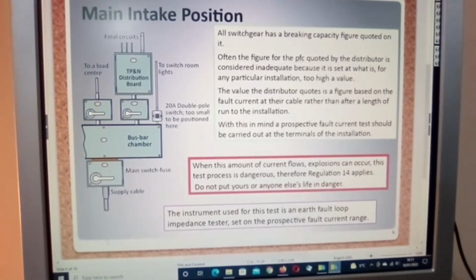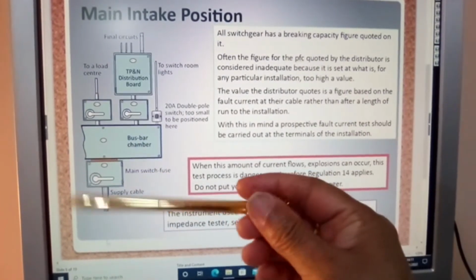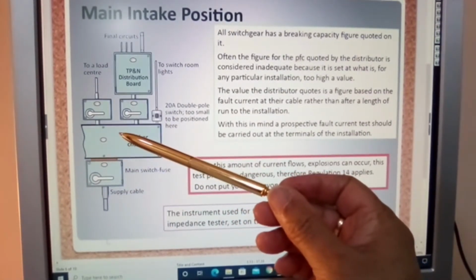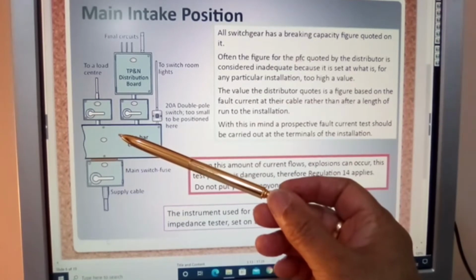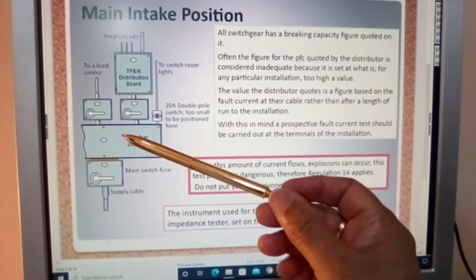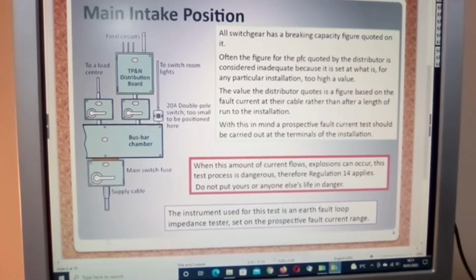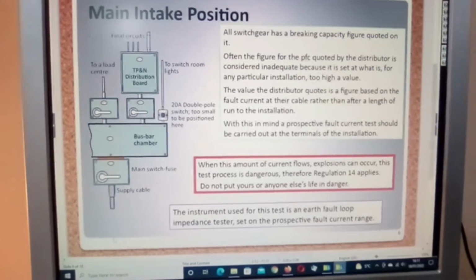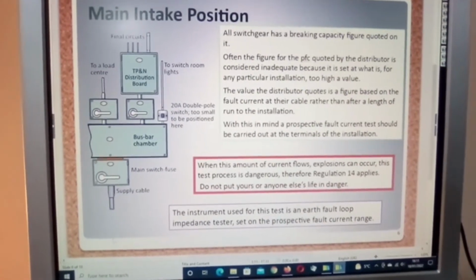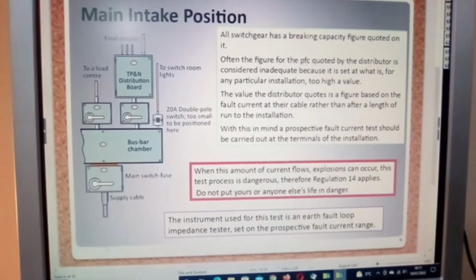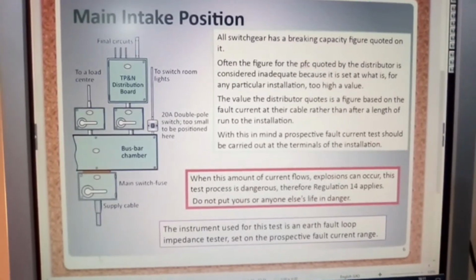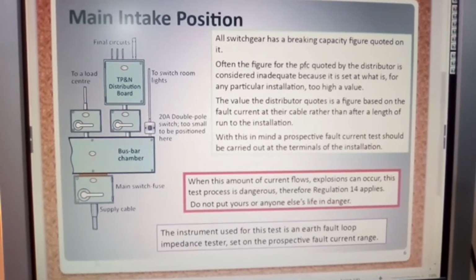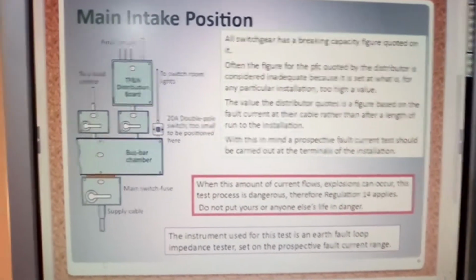Now these are your bus bars. Now bus bars don't actually blow, but they can melt if you have a situation where there is a short circuit in excess of a given value. It will cause the bus bar to melt. That bus bar will then need to be changed completely for a new copper element, okay, or I should say segment.